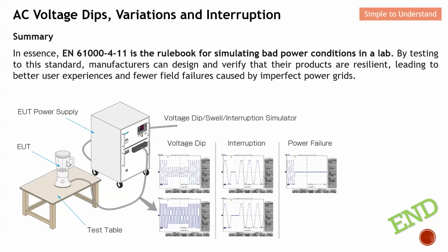Whether it passes or fails the test is actually up to you as the manufacturer. Some devices, like I mentioned earlier, allow for a reset. As long as it can recover by itself, it is certified as passing this EN 61000-4-11 test.